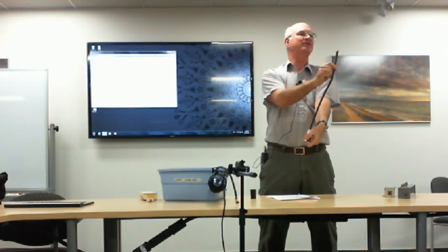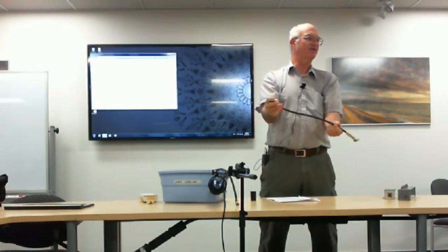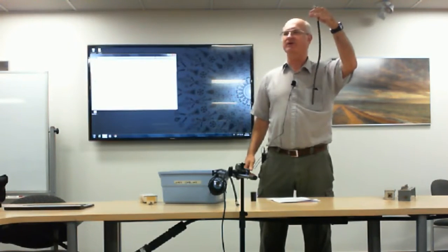That's coming right out of the transceiver? Yeah, that just sits right in the radio. Okay. This is a piece of open-ended coax. Yeah. You simply cut to around the frequency that you want to get rid of, that you don't want mixing in your receiver, and you just leave that in the line permanently of your VHF receiver. And because the frequency that was interfering was far enough away from the ham band, this was able to notch it out. It desensitized the receiver at that frequency enough that it didn't get in, and it didn't cause an intermod. It works.